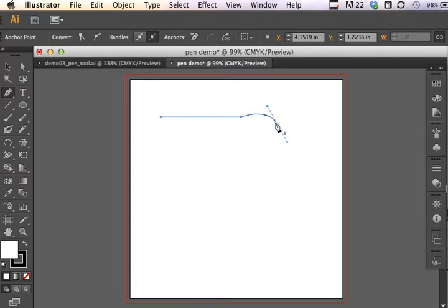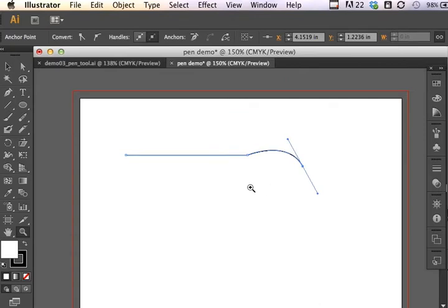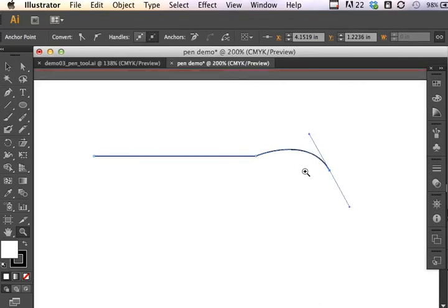You can see that Bezier curve is indicated, and you can see the anchor points that are showing. The anchor points are indicated by the little white squares, and then the filled in blue square is the current point that's selected, and we know that this current point that's selected is creating a curve because it has these two handles on either end.